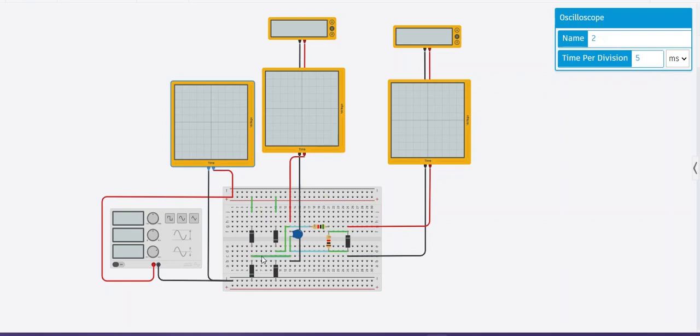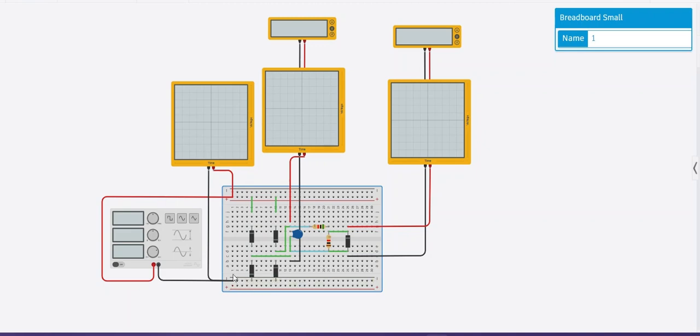And then we have four diodes because we want a full wave bridge rectifier circuit. These four diodes act as the rectifier for our circuit. Then we have a resistor with a capacitor, which acts as a filter, where the capacitance is 5 microfarad.